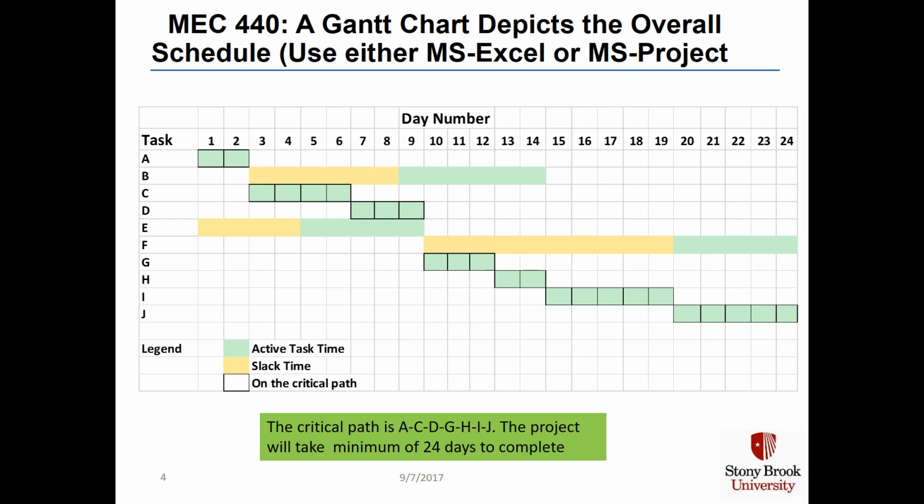There are two types of tasks as shown on the chart. The ones in green with a solid line border around them are called critical project tasks. These are the most time-sensitive tasks. If you don't complete them on time, the entire project will be delayed. Examples of critical path tasks include writing the PDS, creating design concepts, doing component drawings that take a long time to fabricate, buying parts that take 2 to 4 weeks to arrive, assembling your prototype, and testing it.